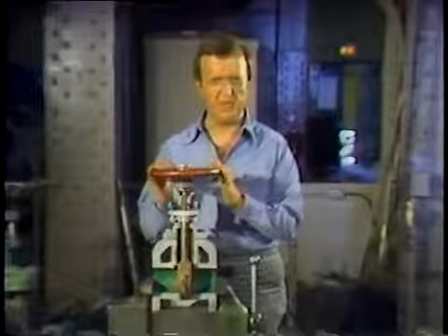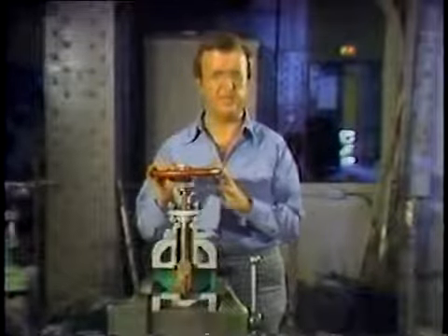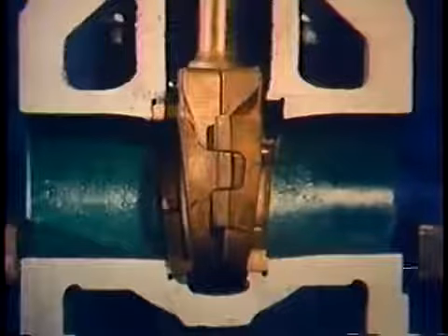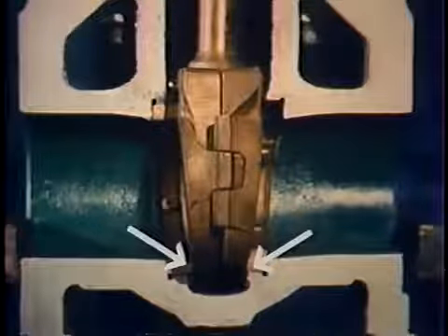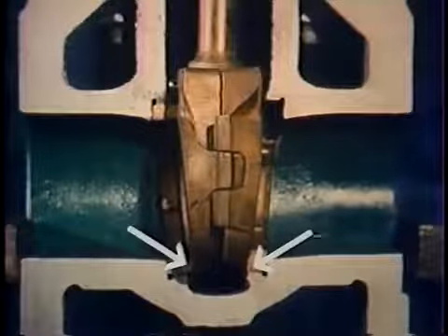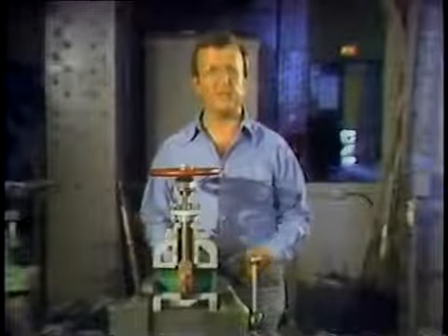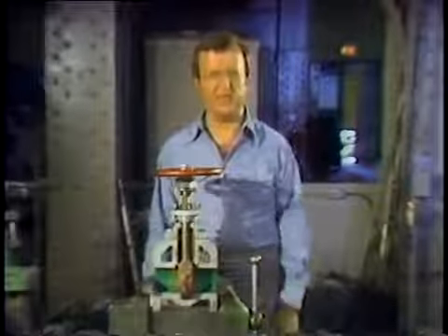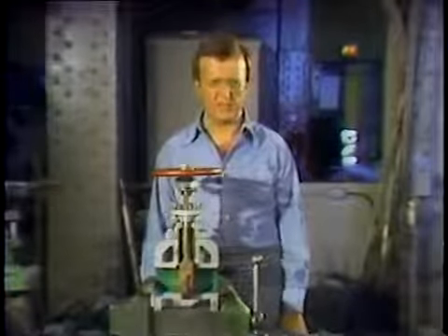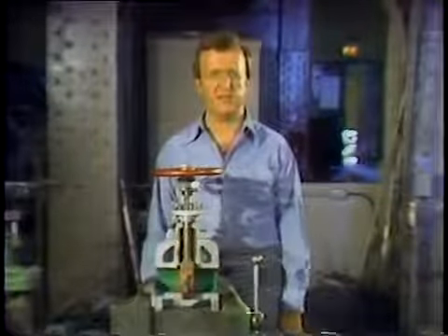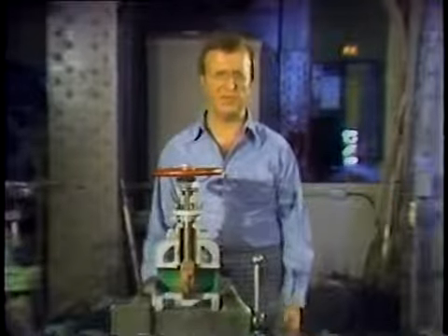It is used primarily for isolating or stopping a flow. The gate valve disc is usually wedge-shaped, and it fits between the seats to form a tight shutoff. Gate valves are made in a variety of sizes, designed to withstand high or low pressure, and are usually found in liquid systems instead of gas systems. They're always either fully open or fully closed.